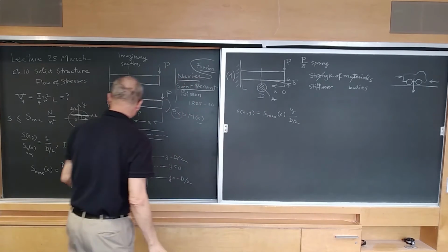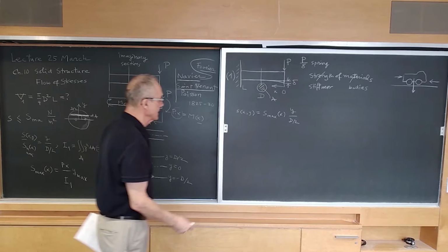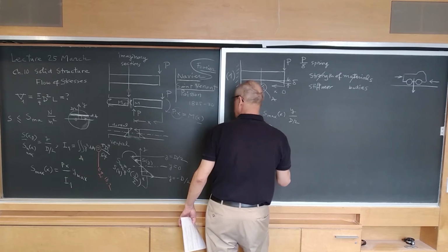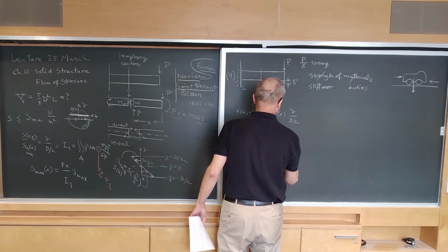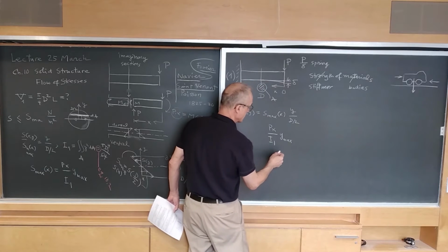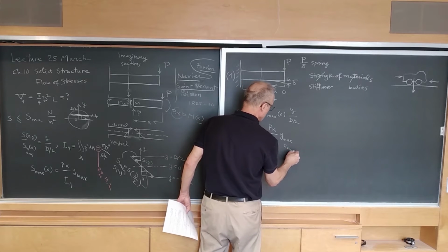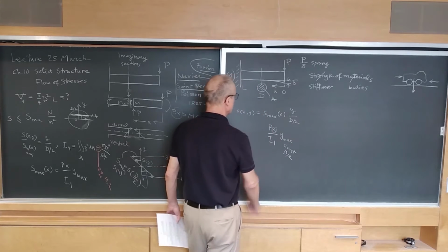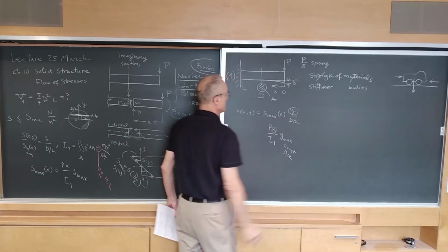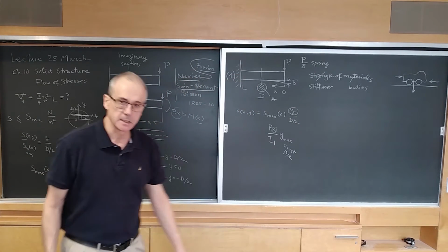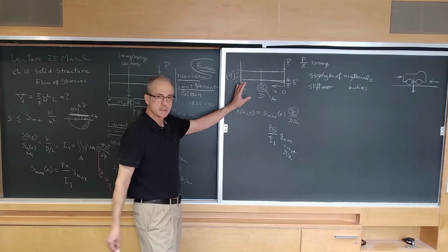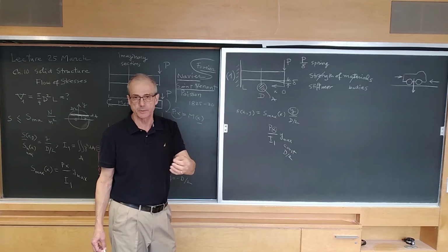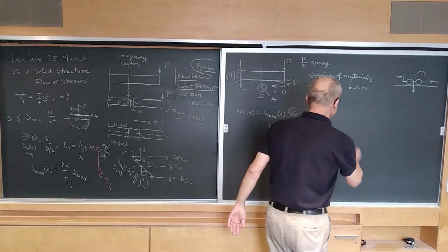S max as a function of x is shown here as linear in x. I write it Px over I1, and then y max. Y max is constant because it is equal to d/2, and this x here is a variable, just like y. And this formula tells us that the stresses that inhabit this cylindrical body are not distributed uniformly. Here's their distribution.